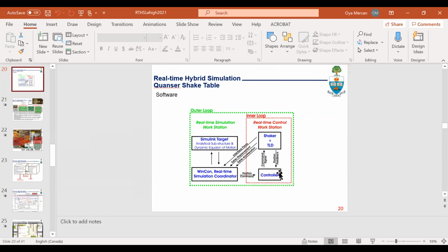And we also introduced a velocity feed forward to fine tune the controller so that it tracks the command displacements better. And although this was a small scale application, you can scale it up as Tommy has provided the additional information. Typically, for example, for MTS systems, the controller comes with the actuator, and even if you can afford to get the real-time hardware simulator, you may have already a platform to use, and you can just introduce your analytical substructure and use it.